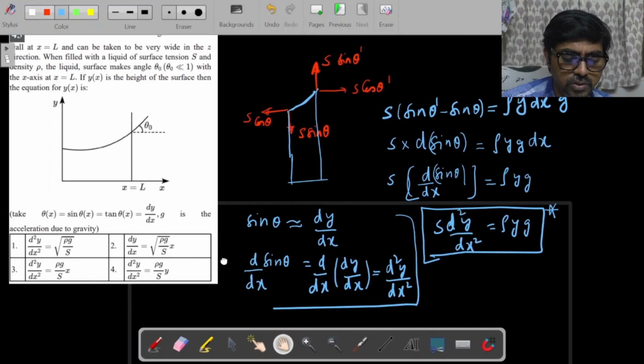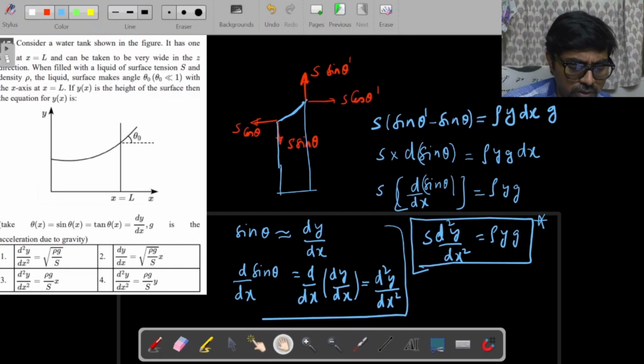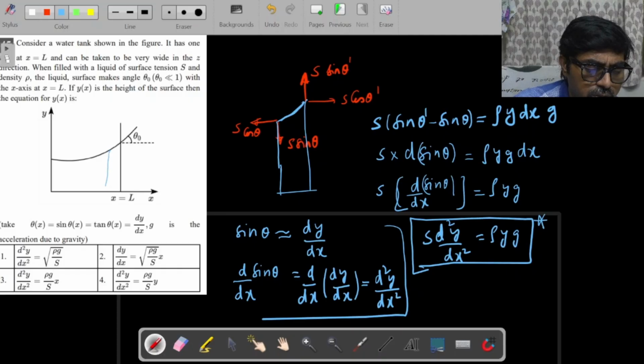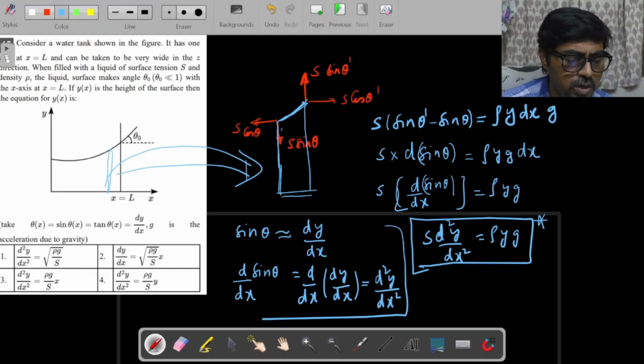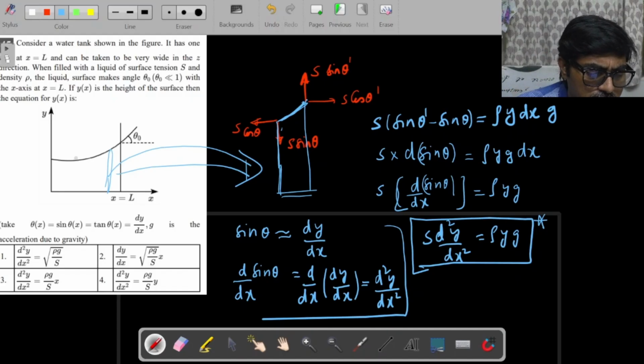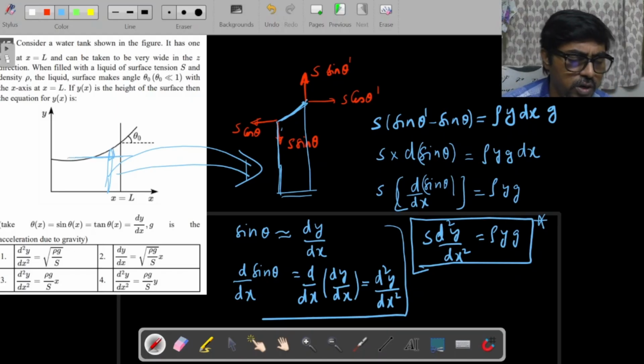I will try to solve it using one small piece of it. So, what I will do is I will take a tiny piece of this element over here and then we amplify it, magnify it and try to look at it. So, the tiny piece will be something like a trapezium type like this. Now you see what is happening. I am not going to take the entire part, I will just focus on only that which is above the free surface. That much only let us consider and draw the free body diagram for it.